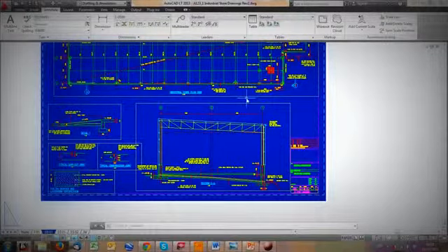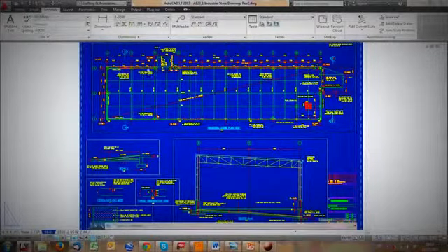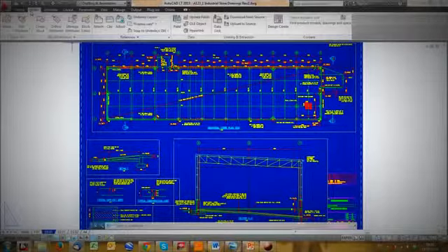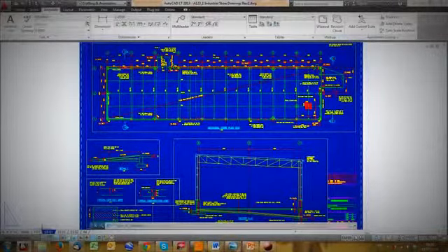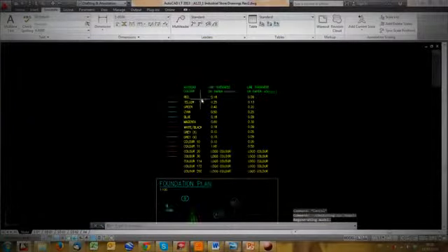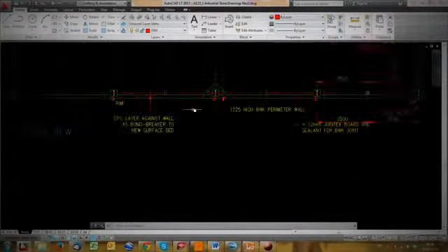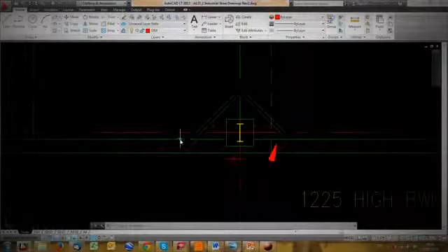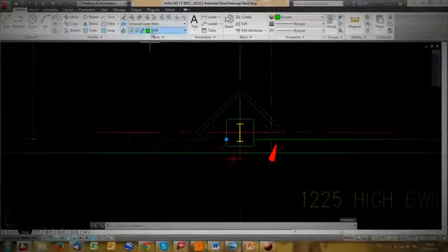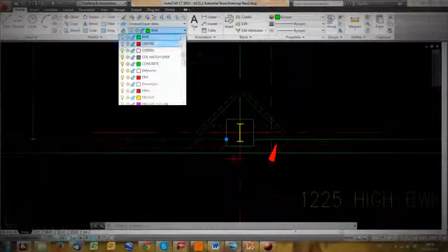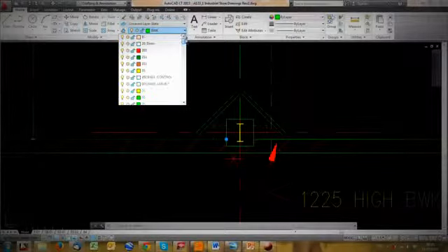Alright, and that's a basic introduction to this. Just one thing I forgot now with those layers and colors. I'm going to go back into model space. Those layers are set here. So if I go to something, I click on it. This corresponds to, for instance, brickwork. BWK, if I'm looking in my layer state here, I've got a list of all sorts of different layers.